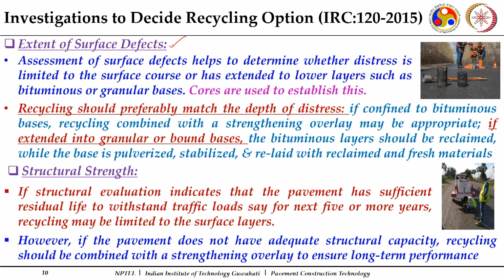Extent of surface defect, as I mentioned, is another important thing which needs to be understood. It is important to determine what type of distress it is and what the extent of that particular distress is, and only then a recycling treatment option is to be selected.